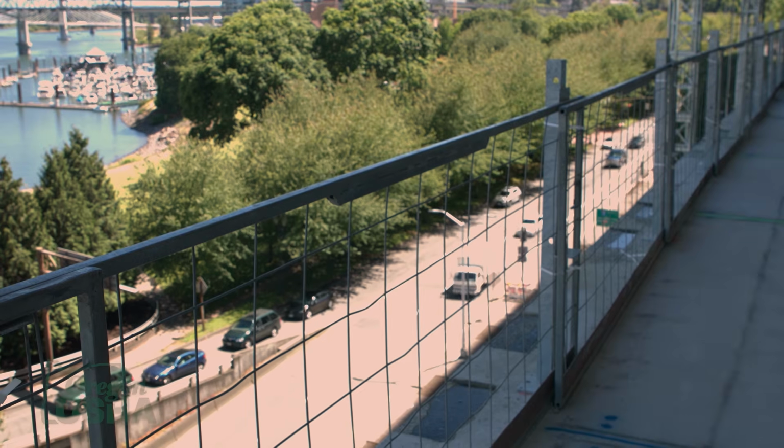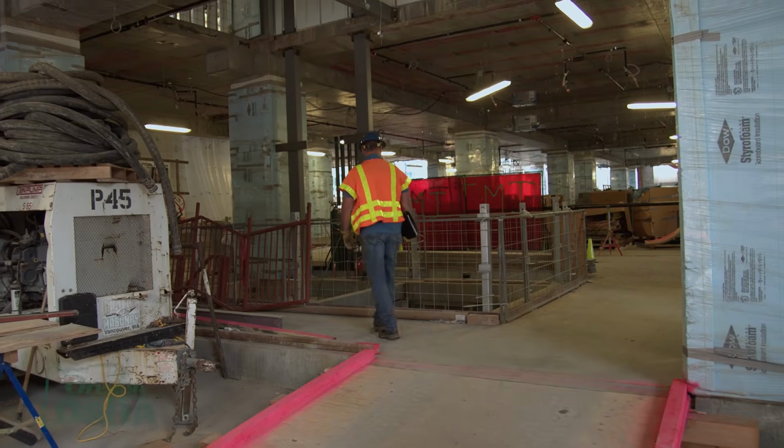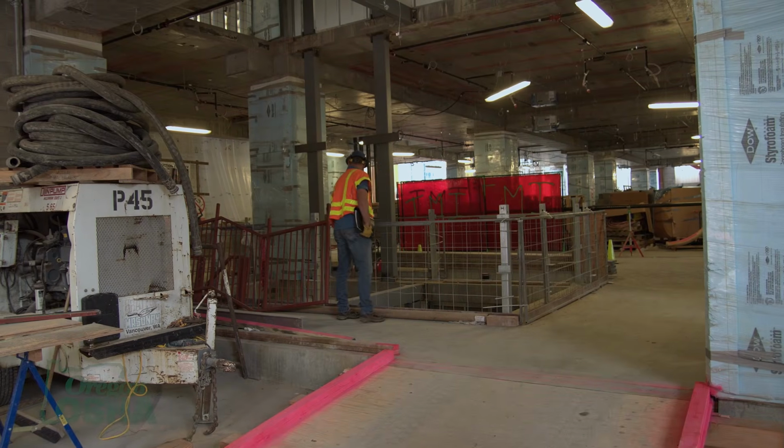Guardrails can be very effective when used properly in fall protection, allowing us to set up a system that denies access to that edge. When a guardrail is set up, it requires very little training from the person who's using it. If I'm using it, when I walk along and I bump into a properly set up guardrail, as long as I don't crawl over the top of it, I've pretty much done exactly what that guardrail was intended to do. It has stopped me from being able to get over that edge.